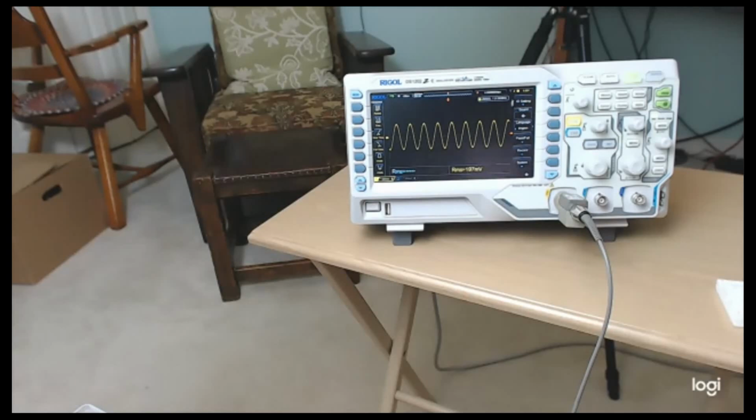So you could use that to test your 40 meter transceiver. You could use it to test a filter if you wanted to plug a known frequency in and see what the bandwidth of your filter is. Or to stimulate the exciter with a known frequency, so you can see how your receiver is working. If you need to calibrate a VFO, all of these things are things you can do with a frequency generator of known signal.